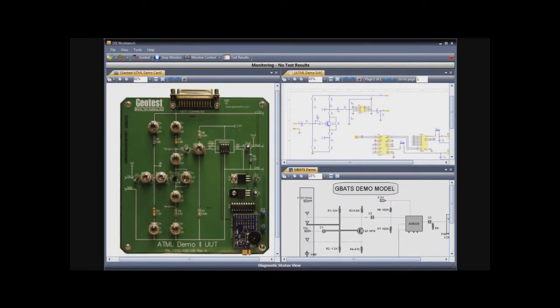On DSI Workbench, the image can be switched to a grayscale viewing style to enhance color contrast that we'll use to overlay on the objects in the design as we learn operational status. You will notice the green bar at the top of the screen, which means no faults were detected. Now that we know the UUT passes, let's go ahead and inject a failure to the UUT.